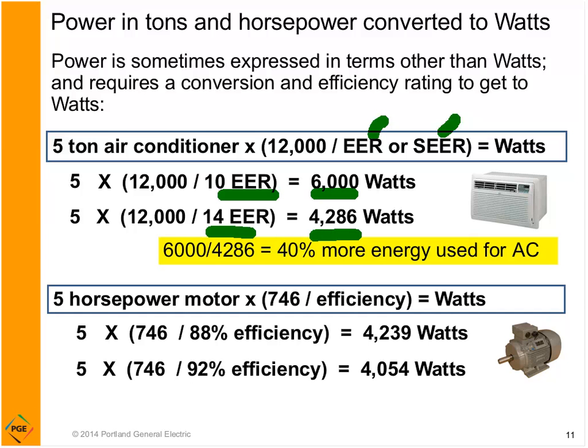If this air conditioner broke, or could be a refrigeration unit, and they came to you and said, wow, I got a great deal on a 5-ton unit, your next question should be, what is the efficiency? If they bought the cheaper unit at the lower efficiency, they just locked in 40% higher energy bills for you for the next 15 to 20 years. So definitely make friends with the purchasing agent side of the house. And get on top of the efficiency ratings of the equipment you're buying.